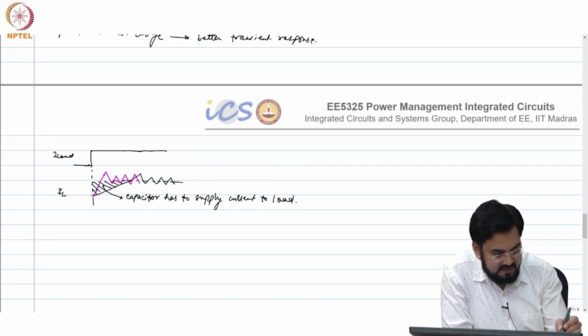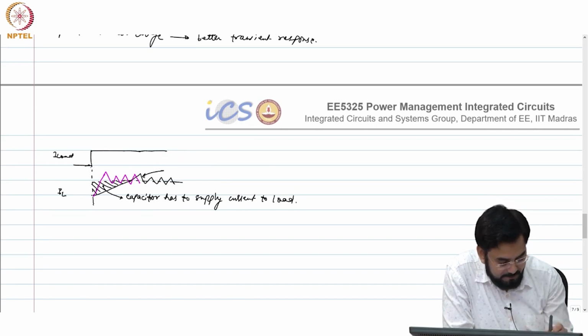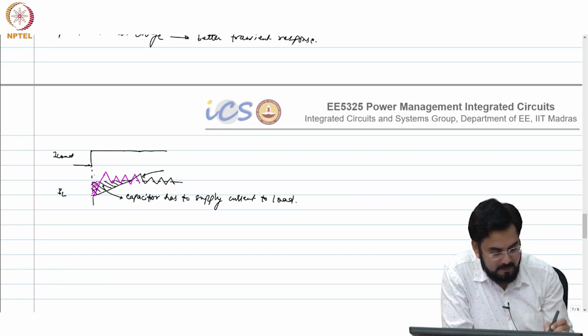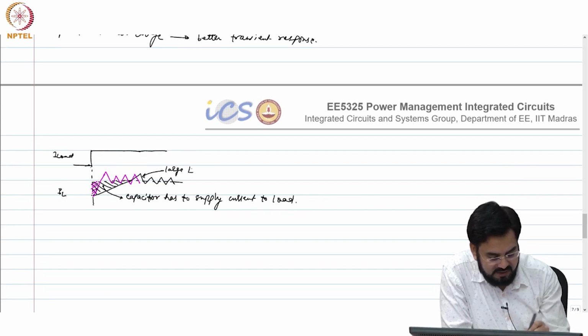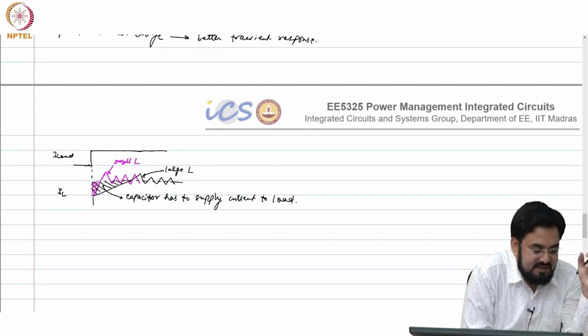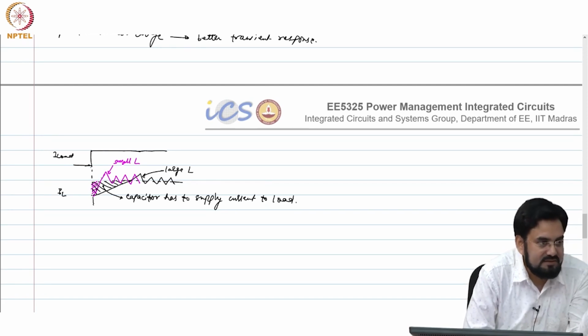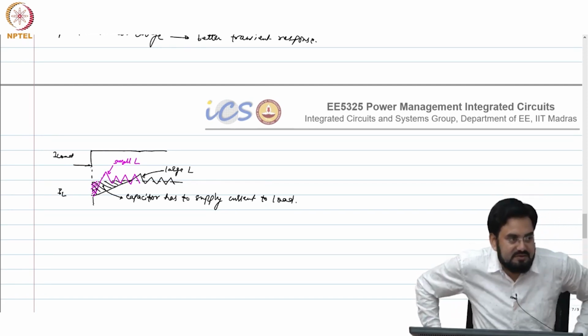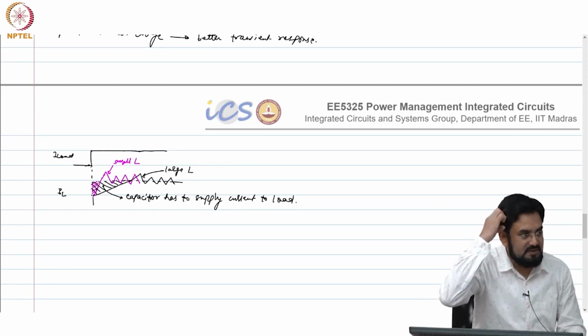So, this is the case with large L, small L. Okay. So, that triangle, actually the area of that triangle is reduced and the capacitor is also increased. So, you get a square factor of reduction in the undershoot or improvement in the transient response.